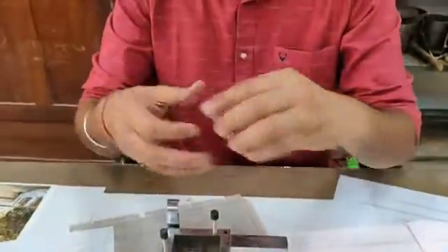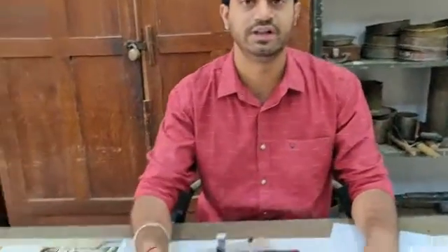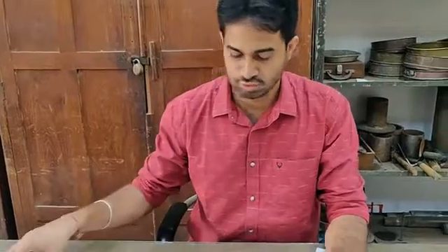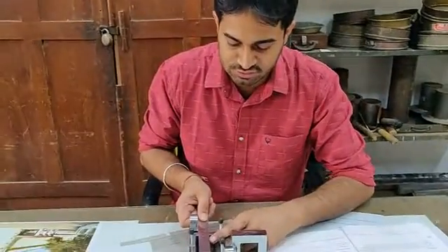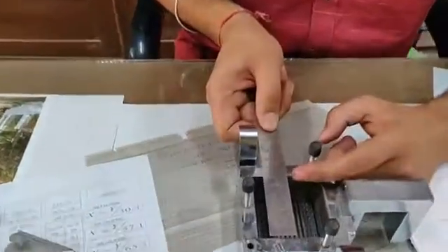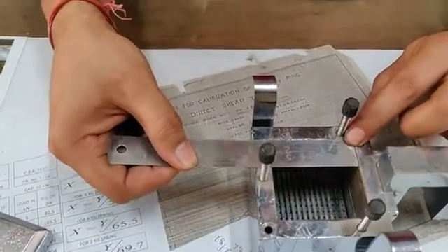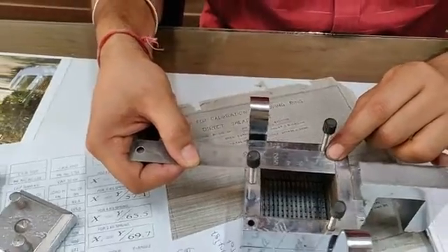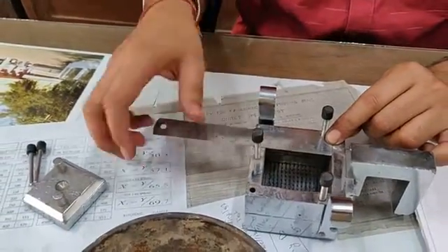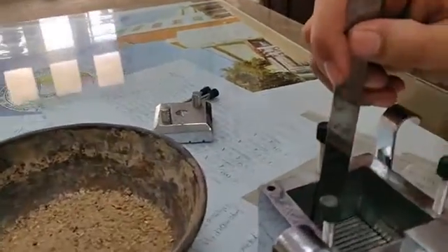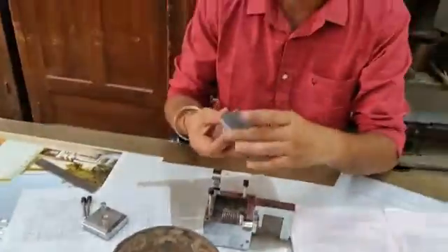And now we will take a soil sample. If the density of this sample is known, the dimensions of this shear box we already know: the height, length and breadth are 6 by 6 centimeter, and we can fix the height of this shear box apparatus, and fill it with the soil sample, the cohesionless soil, which is sand we have taken.